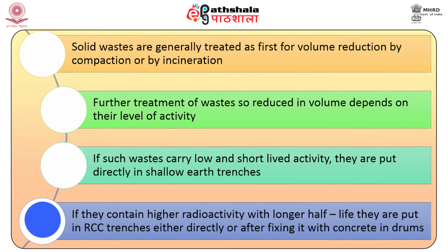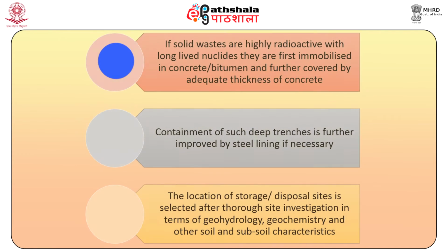If they contain higher radioactivity with longer half-life, they are put in RCC trenches either directly or after mixing with concrete in drums. If solid wastes are highly radioactive with long-lived nuclides, they are first immobilized in concrete bitumen and further covered by adequate thickness of concrete.